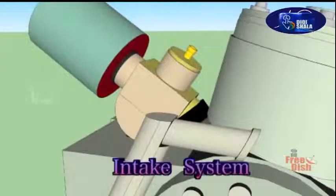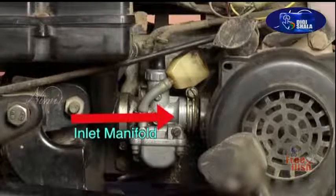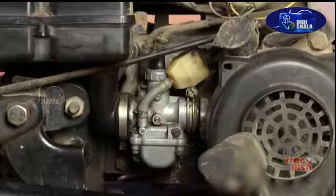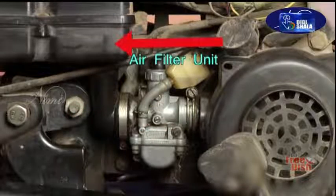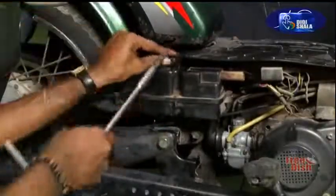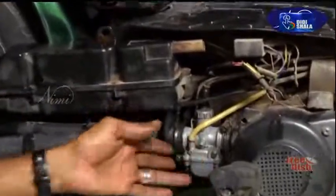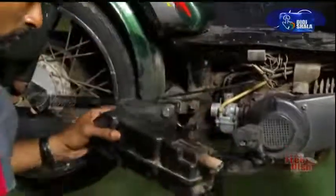Intake system. Intake system consists of inlet manifold and air filter. Using suitable screwdriver, loosen the screws secured to the carburetor and remove the air filter assembly.